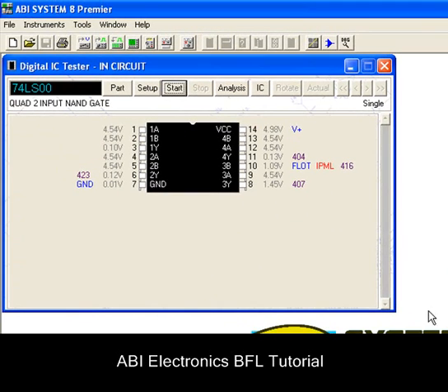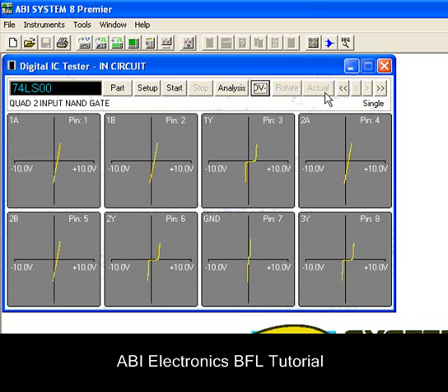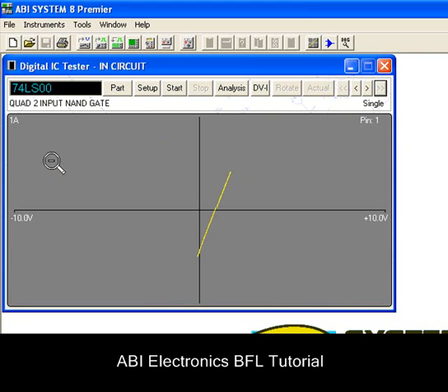Back on the main screen, the results of each test selected provides vital information for the device under test. The voltage results are displayed in grey, the connections in blue, the logic conditions are displayed in red, whilst the thermal results are in purple. For VI results, toggle the view to get the analog signature of each pin of the device. A zoom-in function is also available.